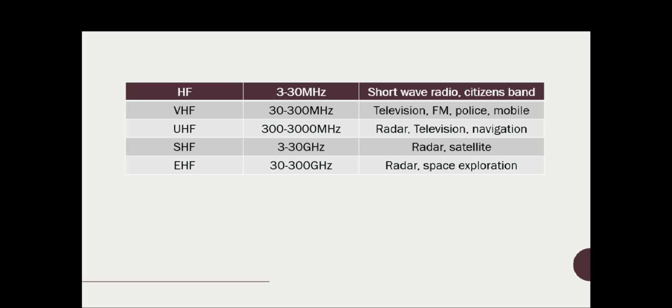So one advantage of knowing the frequency band used by any particular group or agency is that once the offending frequency band is determined, we can accurately determine the source of EMI, if we know this kind of frequency spectrum.